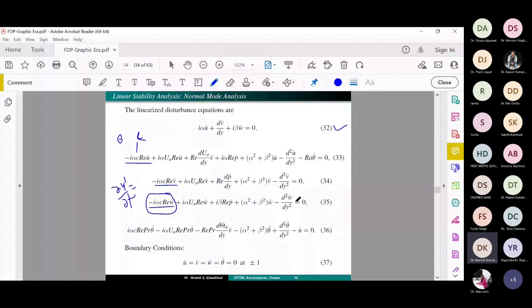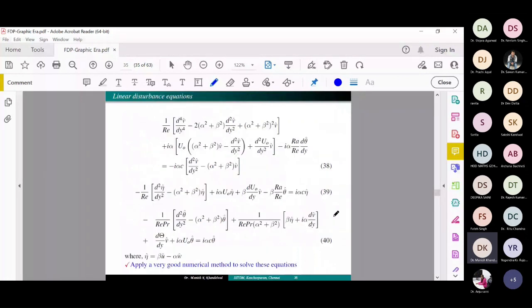That is one of the interesting ways to tackle the problem in a systematic way. When we take the cross multiplication of these equations with respect to P, we eliminate the pressure. After elimination of the pressure, we get a nice set of equations, a fourth order set of equations. This fourth order comes only from the elimination of the pressure, nothing else.